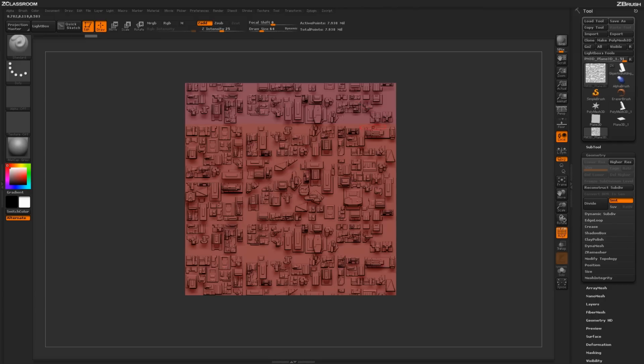So now that I have the top area split or sliced, I'm going to do it down to this bottom area as well. So holding Control and Shift, and dragging out with the slice brush, and then I'm just going to reposition it like so, holding spacebar, and then when I have it where I want it, I'm just going to release, and it should slice through the geometry like that. So now I have 3 polygroups on this actual model here.